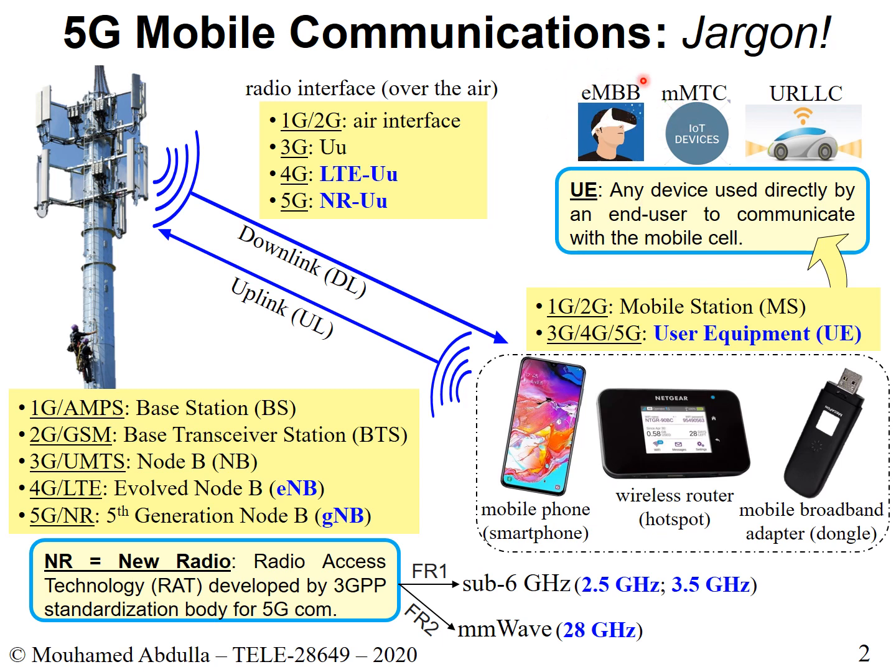So the difference between these two is that eMBB gets a lot of data rate out of the system, very high communication, whereas this one is very, very slow communication. We're talking about somewhere in kilobits per second. But it has the advantage of lasting a long time. If you have a sensor with some battery capability, this battery could last somewhere between 7 to 10 years, so it will last a long time before you need to change the battery. It also has very long communication ranges, somewhere between 10 to 15 kilometers in some cases.